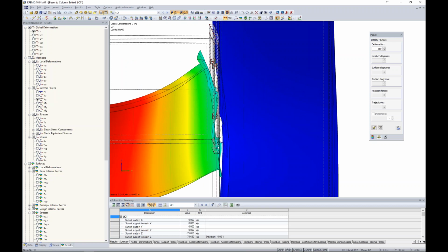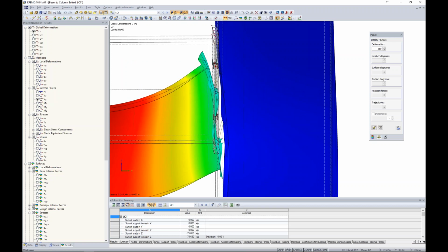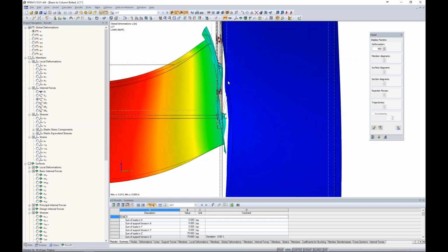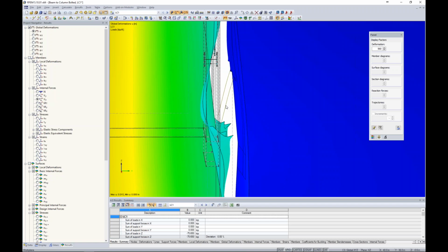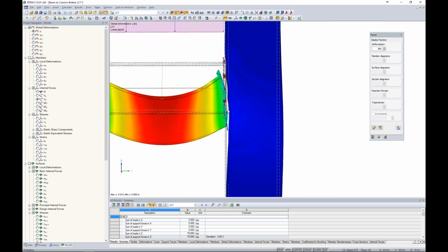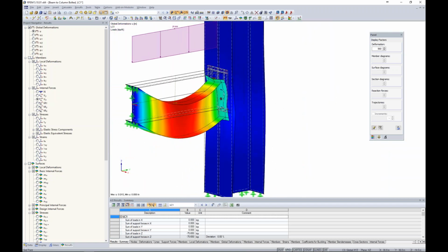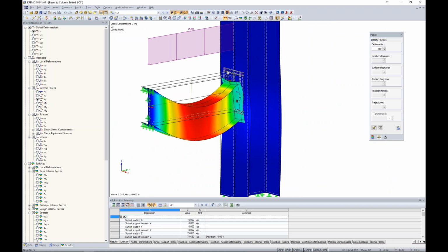As we move along the plate, places where there are compression forces, that's where we should see the full interaction between the 2 surface elements, or actually we have multiple surface elements for these contact solids now. Here are my bolts in tension, of course, as well. So same exact concept. The only thing that I did was split that contact solid into several simpler elements.